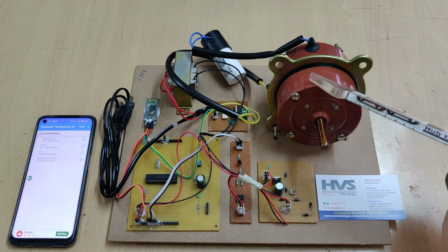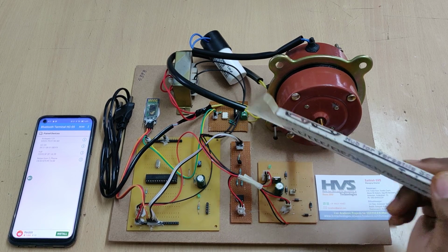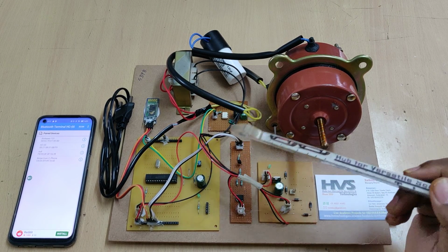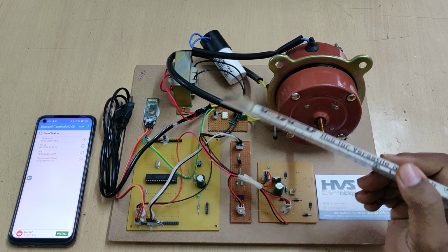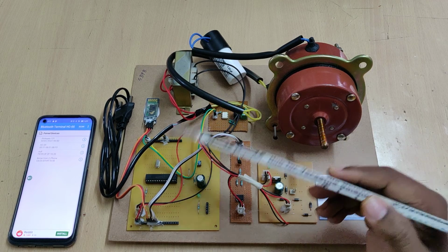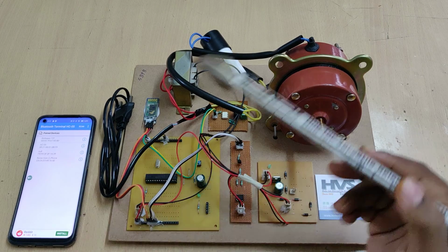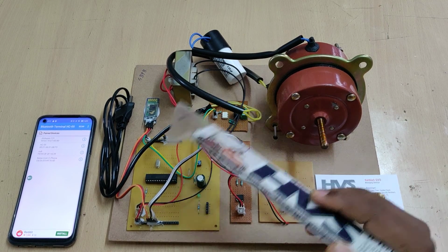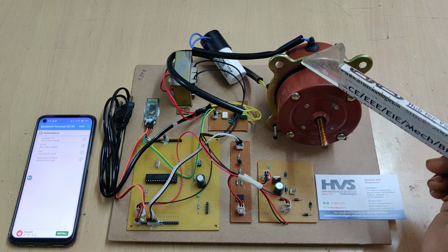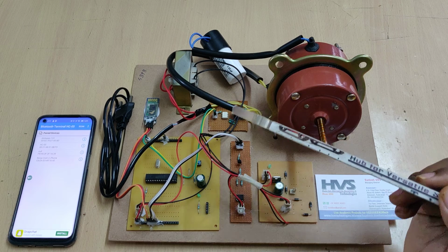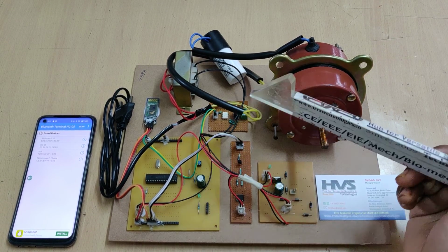To control the speed of the AC motor, we are going to use two major components: one is the triac board and another is a zero crossing detector. In DC, if you want to control the speed of a DC motor, we can directly use a transistor or a MOSFET with the PWM technique, because there is no zero crossing. The voltage only starts from 5 volts or 12 volts. But in AC voltage, the alternating current, we get 0 and 230 volts and 0. That is the variable current.